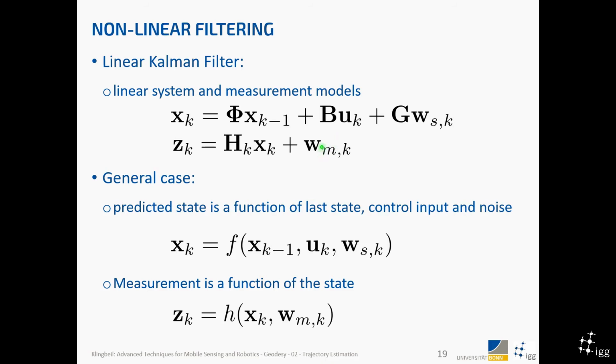Good. What we see now is that we can use inertial sensors to calculate position and orientation, to update position and orientation every time we get a new measurement, assuming that we know the starting values of position and orientation at some time. And what we have also seen is that the error, the uncertainty of this estimation, becomes bigger and bigger with time. And it goes quadratically or even cubic with time, depending on what we look at.